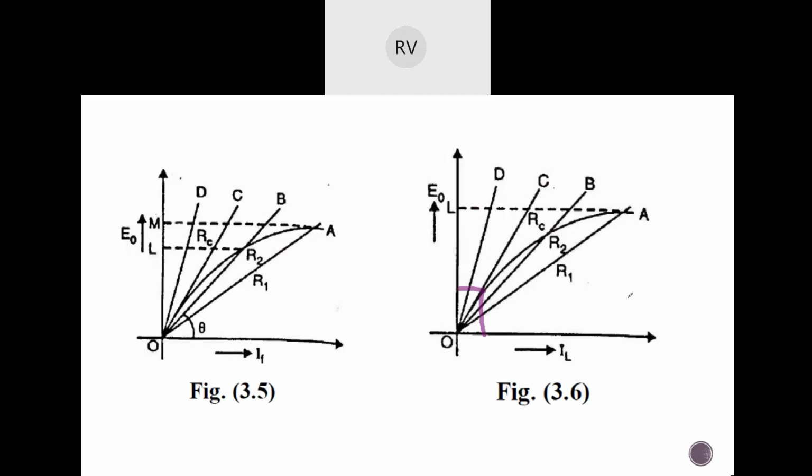So when we go for the experiment part of this, we are going to draw an OCC. Along with drawing an OCC, we'll find out at which field resistance, or at which resistance, this particular machine gets its critical field. We need to find out the critical field value.